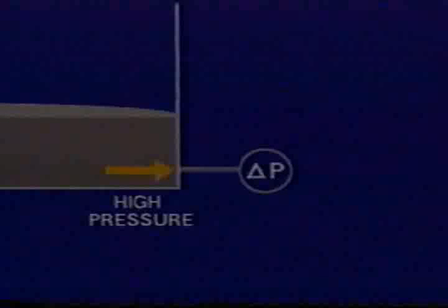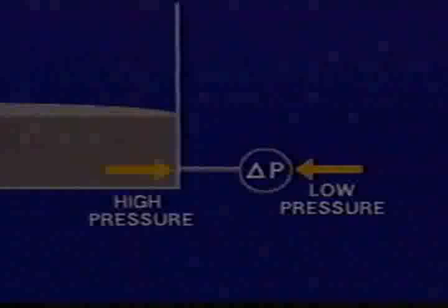For hydrostatic level gauging of open tanks, a differential pressure transmitter is often used. Here, atmospheric pressure is input on both the high and low side of the transmitter. The high-pressure port senses the atmospheric pressure on the fluid in the tank and the hydrostatic head pressure. The difference between the pressures can be converted to level. The low-pressure port senses only atmosphere.